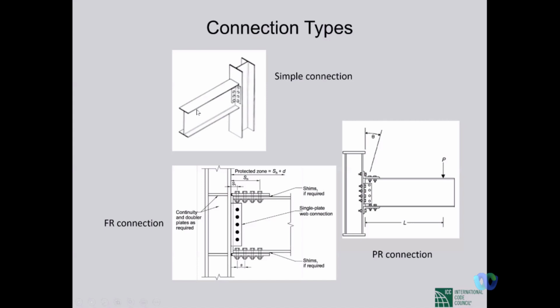The moments about the strong axis produce maximum stresses along the flanges of this I section of the beam. So the flanges of the I section of the beam should be rigidly attached to the columns if we want to transfer the flexural stresses.